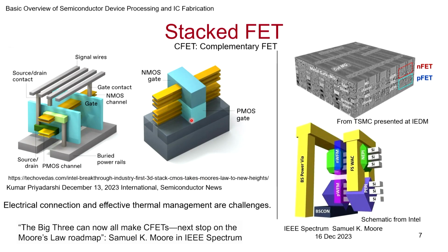So typically what you do is you have a P MOSFET. On top of it, you build an N MOSFET. It turns out that today's technology allows it. And also, some of the tricks that they do is they make the P MOSFET with silicon germanium or germanium itself. On top of it, again, bring back silicon. They use such tricks.